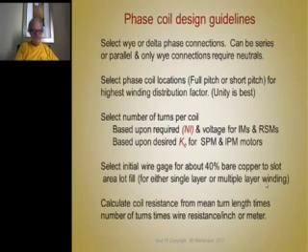So what you need to do, whichever one of these wye or delta connections you pick, and slot and pole numbers, you've got to select where the coil locations are, whether they're full pitch or short pitch, so that you get the highest winding distribution factor. And then you select the number of turns based on the required ampere turns and voltage for induction machines and reluctance synchronous, and based upon the voltage constant required for surface mount and interior permanent magnet machines.